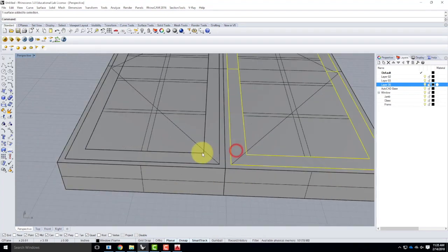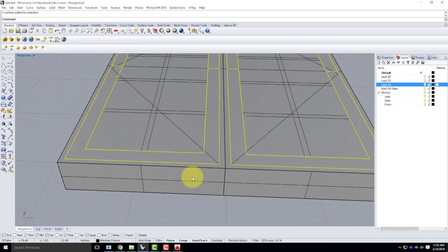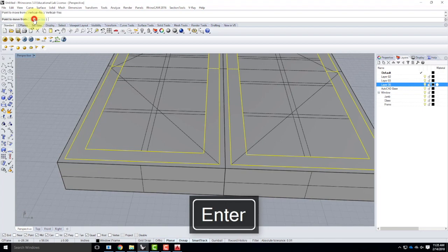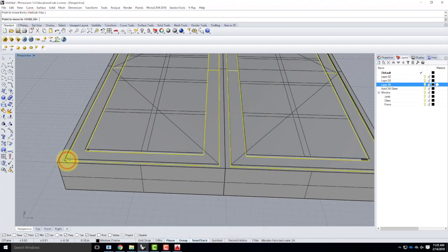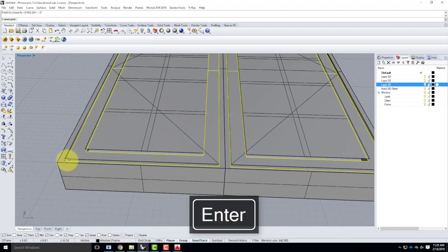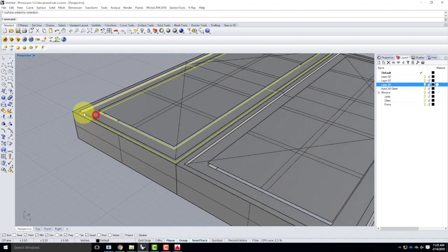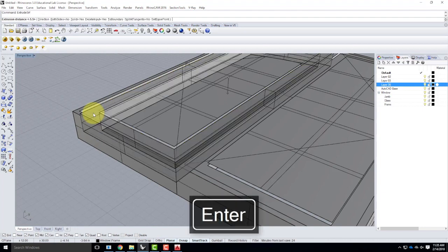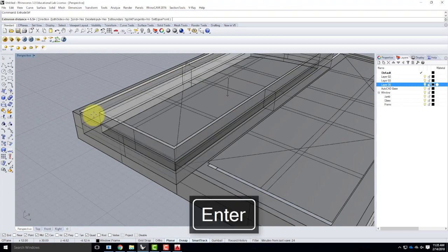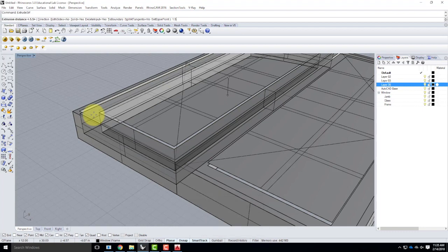Now this next part, the frame, is probably recessed back a little bit. So let's move it. I type move, vertical, I don't know, by ½ inch, 0.5. Sorry, negative 0.5. So that then goes down a little bit. And then we could extrude those pieces. So extrude surface. And so maybe those are, I don't know, 1.5 inches. Negative 1.5 inches.